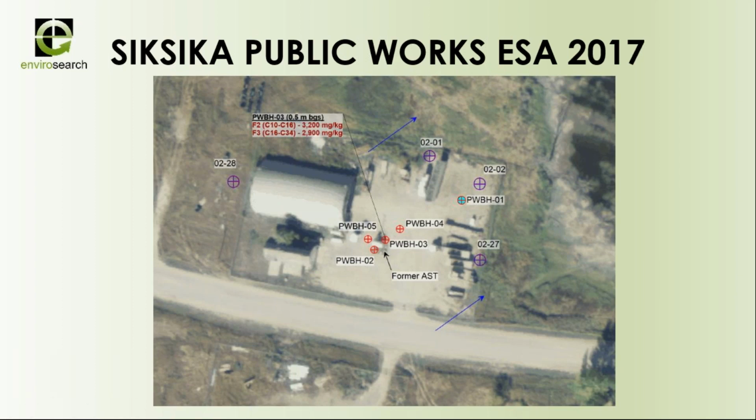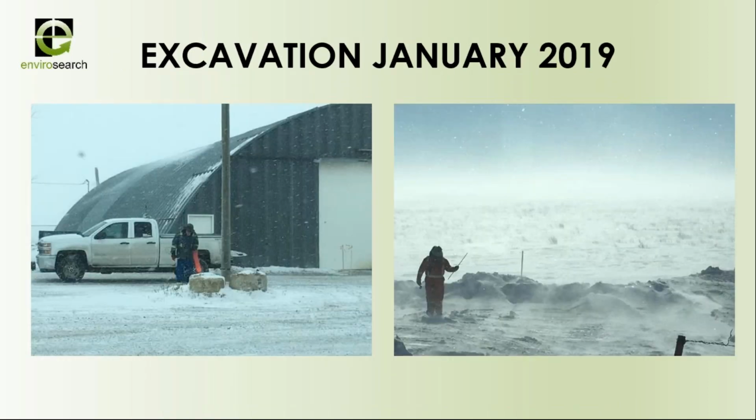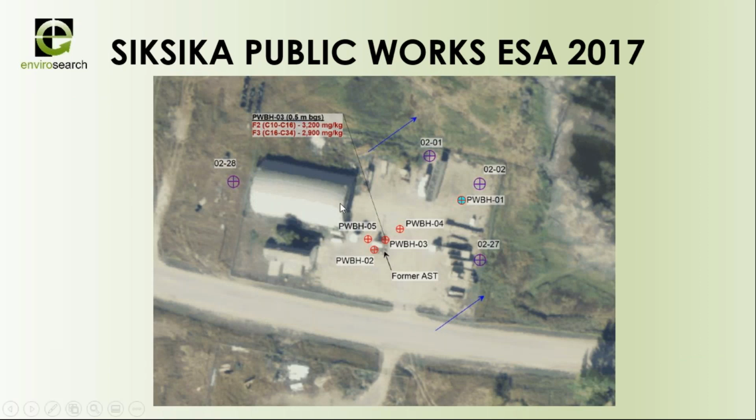And I think, like many projects, there were budgetary constraints on the amount of investigation that could be completed, particularly knowing that it was going to go to excavation. During this site investigation, this one borehole had F2 and F3 hydrocarbons present above the relevant guidelines, with the other 3 boreholes near that one all below guidelines.